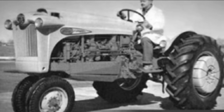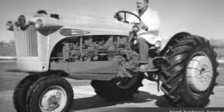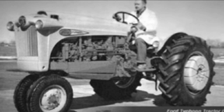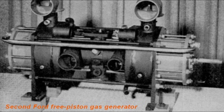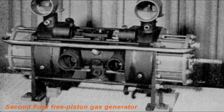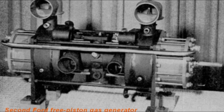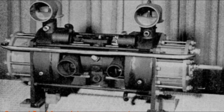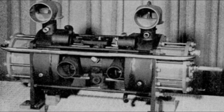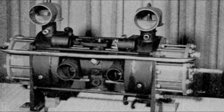Attempts to improve performance by increasing boost were unsuccessful. This increased the heating of the gas generator's cylinder piston assembly. Overheating also increased heat loss. The gas generator suffered from insufficient stability due to changes in piston stroke length at different operating modes. This was especially noticeable at partial loads, where misfires occurred. Misfires in such an engine were a significant problem, as it lacked an energy storage device, such as a flywheel in a conventional diesel engine. A number of other problems were also reported.